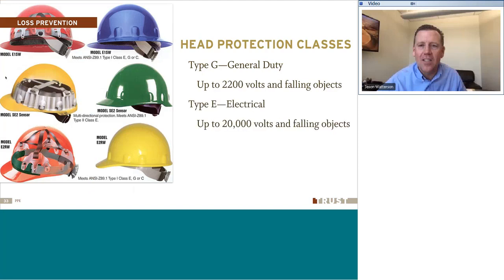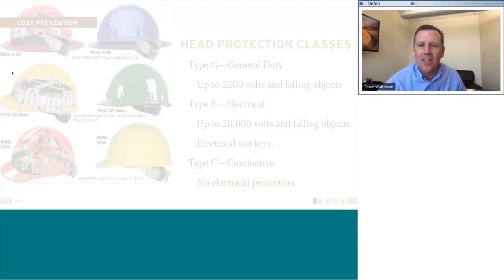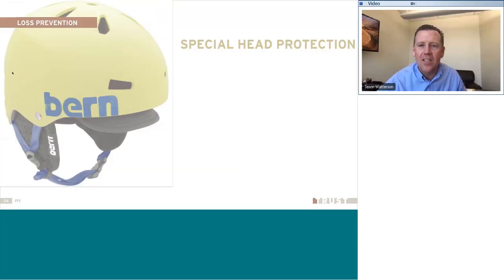I'm working on a construction site where there can be nails or other sharp objects sticking up. Our safety shoes need to meet these standards. There are actually two different standards. OSHA still calls out the ANSI Z41 standard, but most of the footwear that you'll buy now will list the ASTM F2413 standard. That's the actual performance standard that shows what they will do.